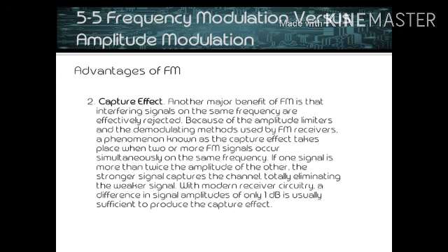Although the capture effect prevents the weaker of two FM signals from being heard, when two stations are broadcasting signals of approximately the same amplitude, first one may be captured and then the other. This can happen when a driver moving along a highway is listening to a clear broadcast on a particular frequency. At some point, the driver may suddenly hear the other broadcast, completely losing the first, and then just as suddenly hear the original broadcast again. Which one dominates depends on where the car is and on the relative signal strengths of the two signals.